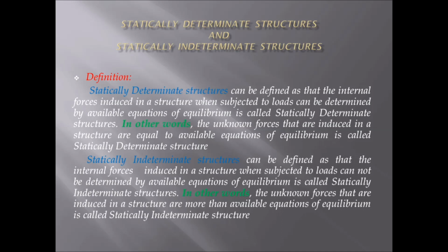In other words, if the unknown forces induced in a structure are equal to the available equations of equilibrium, it is called a statically determinate structure. We can discuss this elaborately. Whenever loads act on a structure or a member, internal forces are generated against the loads. The forces or reactions generated should be equal to the available equations of equilibrium. Then only is it possible to determine the structure, and that is called a statically determinate structure.